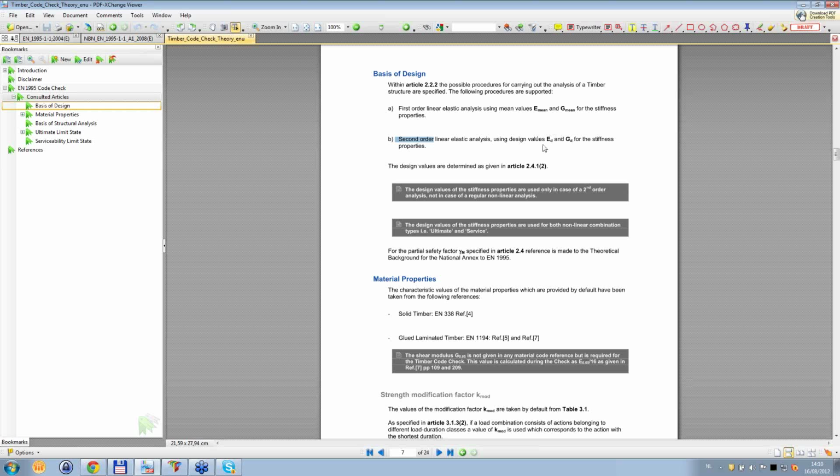So this is quite an interesting difference from steel. Those of you familiar with steel will know that this rule in fact is not that new. In steel this is, for example, also used in the DIN code. So now it finds its way also in timber. Okay, so this is fully automated, automatically implemented within Scia Engineer.